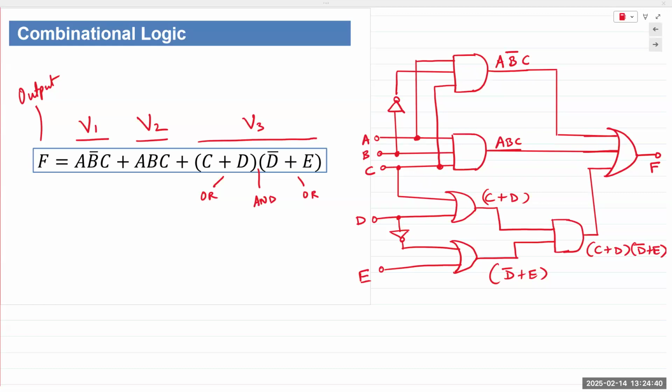So we have to count all of those. Oftentimes, as we saw in the previous class, we would take a NAND gate or a NOR gate, and we'd create an inverter using those gates. So in real life, if you were implementing this logic, we'd have a bunch of NAND gates, and we just implement using this logic.